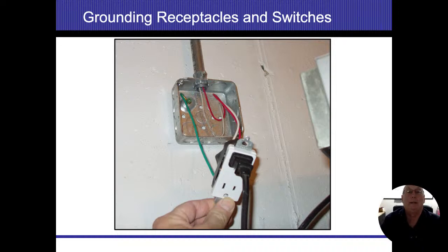Right now we just have a 1900 box. There's supposed to be another plate on there that I could screw the top and the bottom of the outlet on. But at least they went ahead and put another ground wire from the outlet to the box. And as long as that box and all the conduit going backwards is all connected, then even if I remove that outlet, I am still grounded. Otherwise, if that outlet was loose and free, it wouldn't be grounded. The only way I would be able to ground it is to get those metal prongs touching it again.